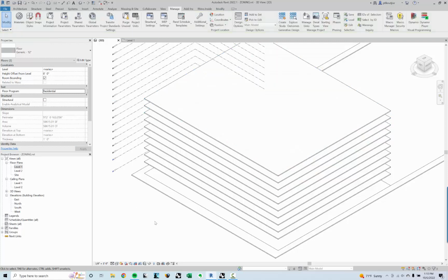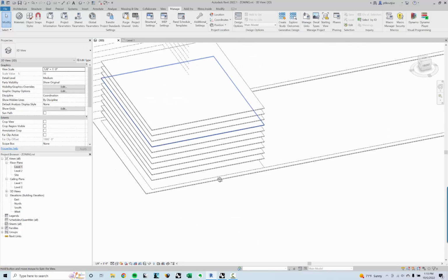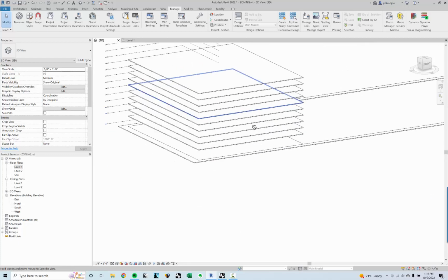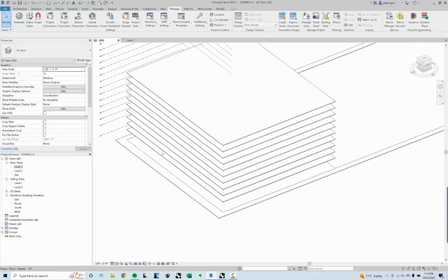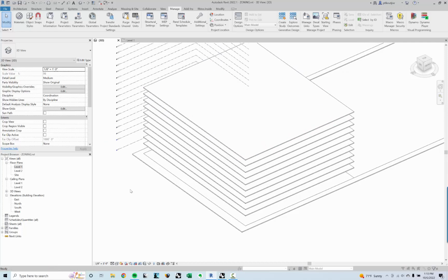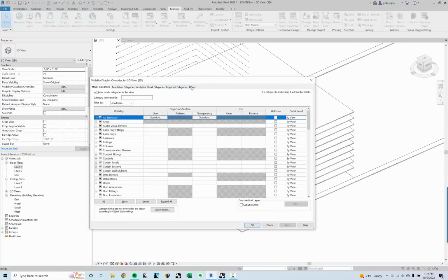All right. Now that's great, but it's hard to now tell which is which, right? It's all just embedded in there and I can't visually identify which is which. So I could create duplicate families or something like that, but I actually usually don't like to do that. I like to use the family itself to talk about the constructability and the type of the thing, but not a parameter associated with that. But luckily Revit has something called filters, which will allow us to work with that.